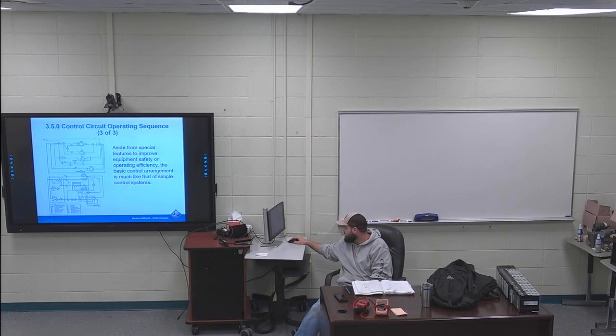You're going to have a question in the heat mode. So it's going to say what happens as soon as I turn it to heat mode and the thermostat's calling for heat. So if it's calling for heat all the way to right here, you're going to get your wire going to the IDR. I look down here on what IDR is, and that's my induced draft relay. So my relay going to my IDR contact up here.